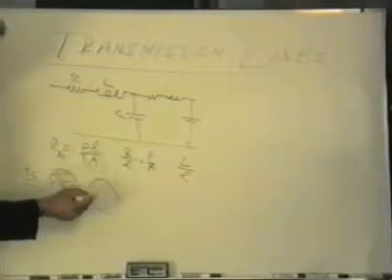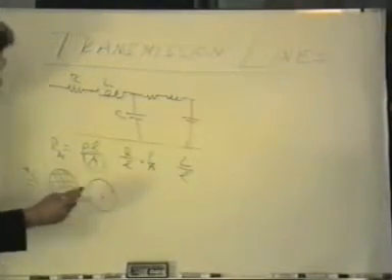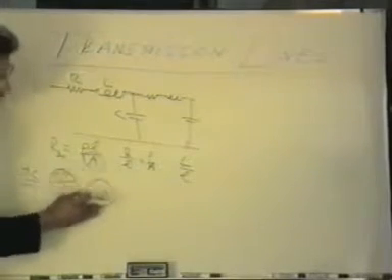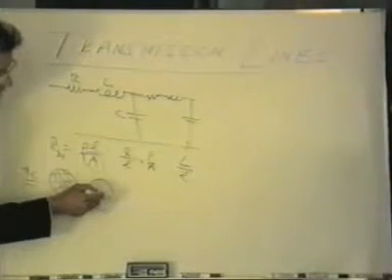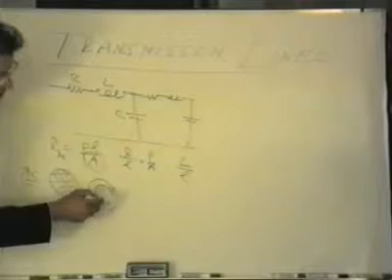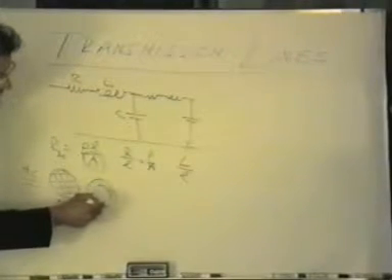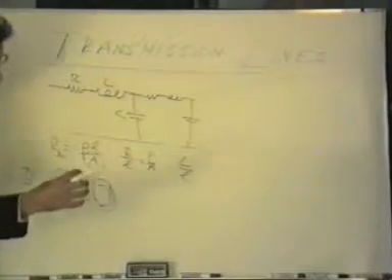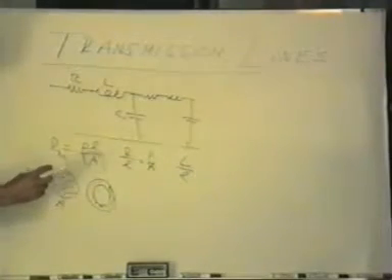When AC current is flowing in a conductor, instead of flowing into the board or out of the board as the case may be and using the whole cross-section area, it tends to travel around the edges so that the electrons are in this outer ring and they're moving out or moving in on the conductor.